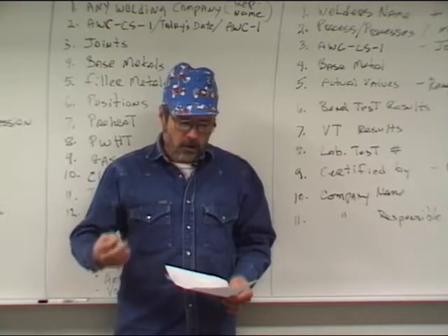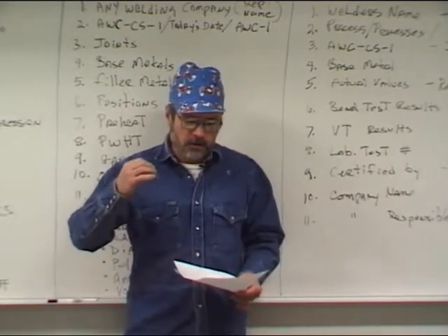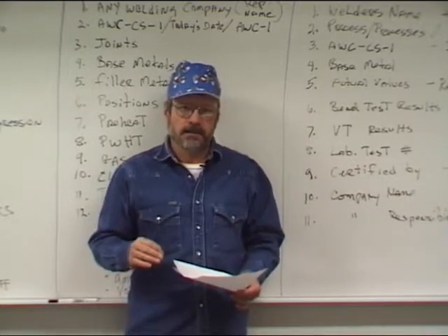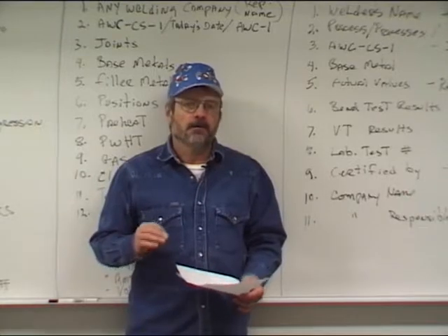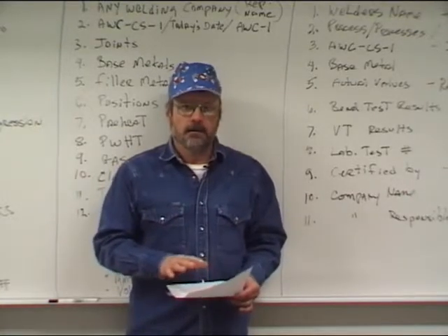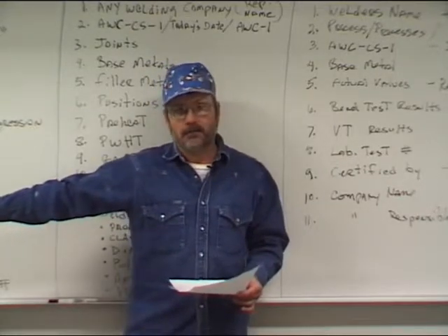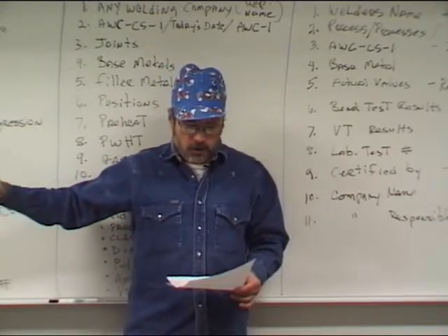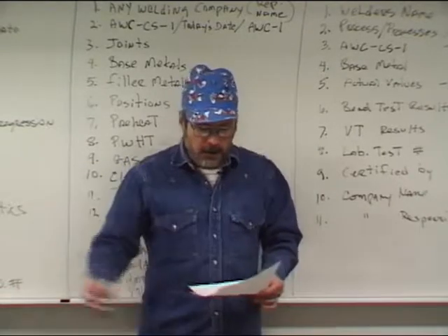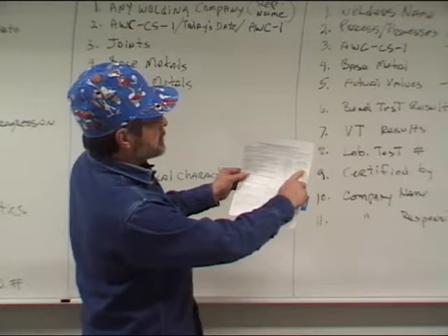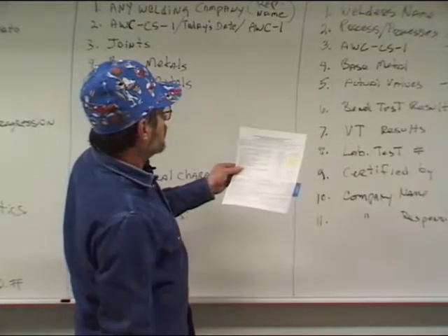So we will restrict them to the given filler metal only. And if we need them to weld on stainless, that is beyond the range of this qualification. We limit it so that we won't be having them out there welding stainless when they're not qualified to weld stainless. So we write in that block, given filler metal only. So right here where it says F3 and F4, the next line over, given filler metal only.